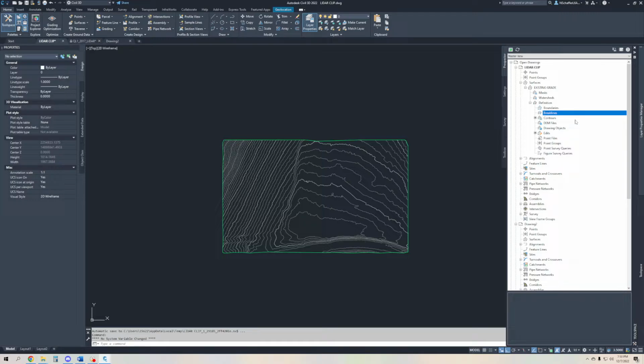And you could pull them up slightly, you can move them around, but those quote-unquote break lines are going to stay where they're at. Those are your points and your elevation points that you have. So those can be created with feature lines, and we'll talk about that here momentarily. We've already talked about contours. Next is DEM files. So if I had that image ready to go, I could load that DEM image into this edit and add that in, and it'll create my DEM surface.